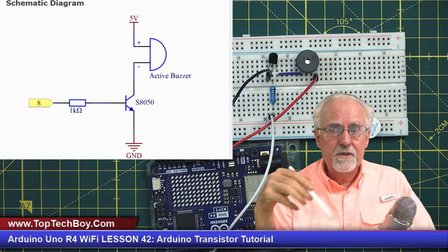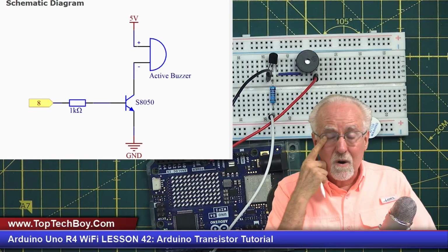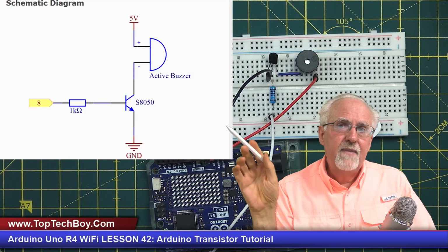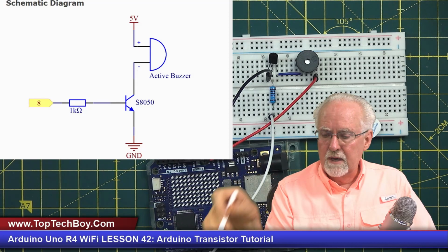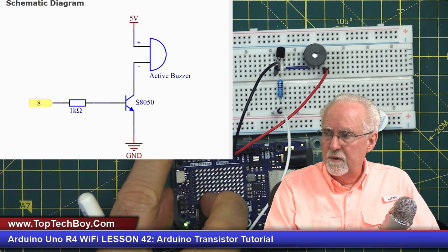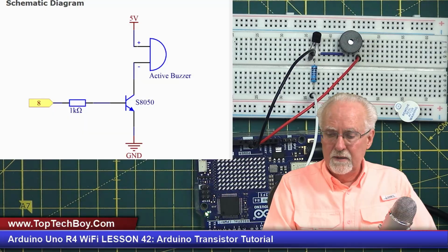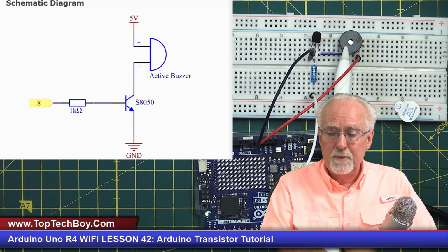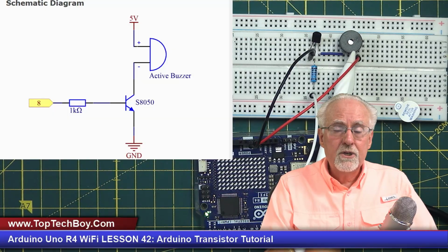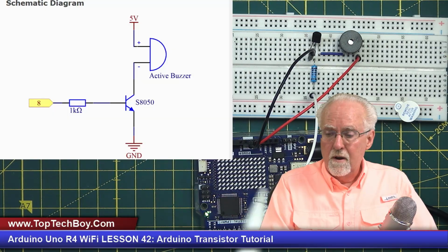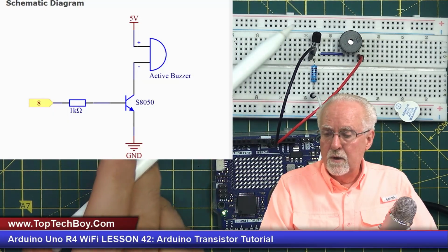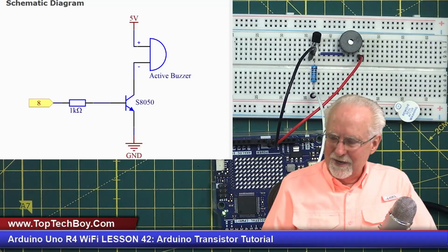If you just start trying to turn the motor on and off without doing a little bit more circuit design, that impulse current from the motor could come back and burn out your Arduino. So you want to wait till we show you how to do it, but a lot of it will be the same concept. We will be controlling a large current that runs the motor from a small current on the Arduino GPIO pins using a transistor.